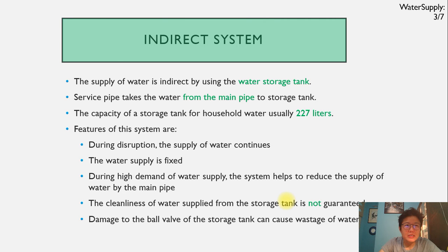Alright? Because it's debatable. You say that if the water coming in from the main has been treated in the plant, when it comes, it should be clean enough. But as we said, cleanliness of the water quality is a very subjective matter. If it is safe to be distributed, meaning that there may still contain some sediments, but the water itself is safe. And some sedimentation is expected to take place in the storage.